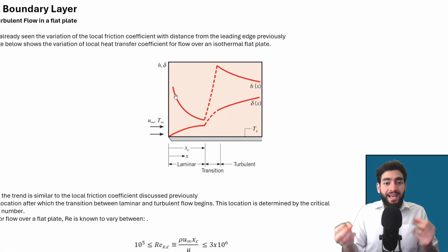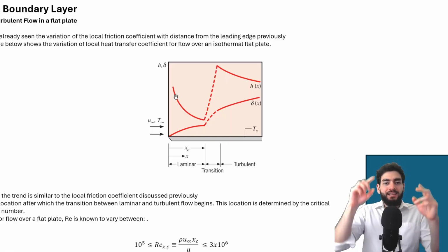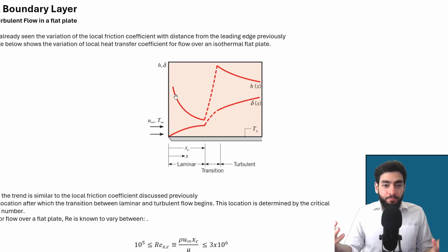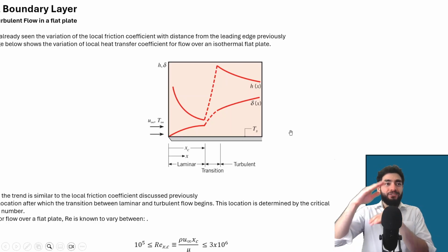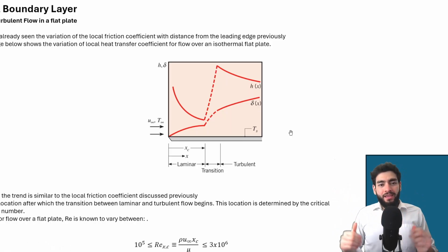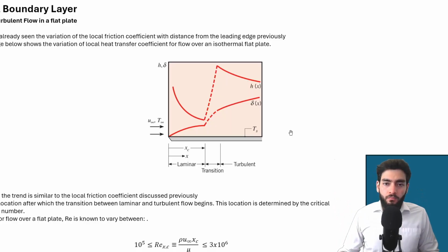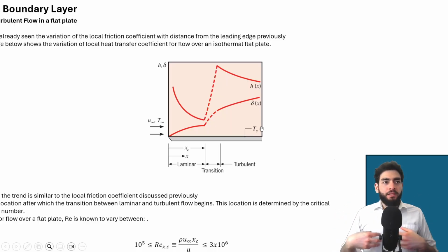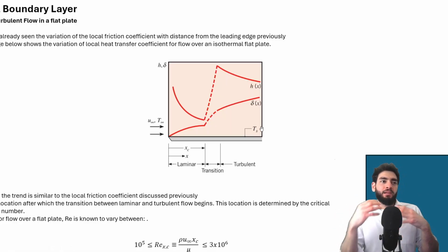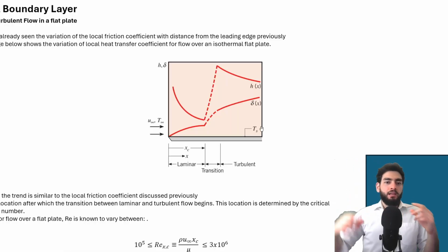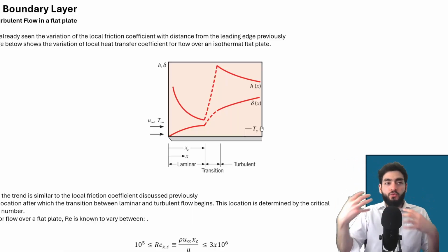That's because the gradient of the temperature evaluated at the surface of the plate decreases the farther you go from the leading edge. One way to look at it is that the boundary layer thickens, and so we did find ways to reason through it.